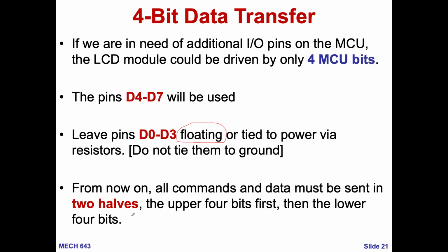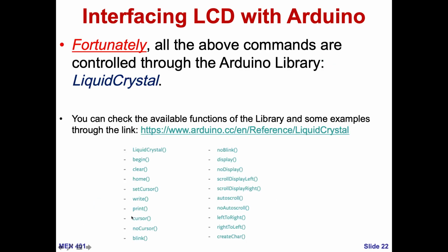How do we interface this LCD with Arduino? Fortunately, everything that I have discussed before does not apply in Arduino, because we're really working with high-level programming. So what I will do is add the Arduino library, LiquidCrystal. As we saw in the lecture, it's a collection of functions that can help us communicate with this LCD at a high level. We do not go into details as I showed you at the beginning of this lecture.